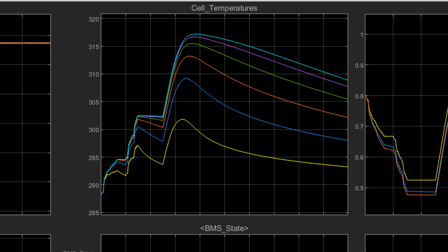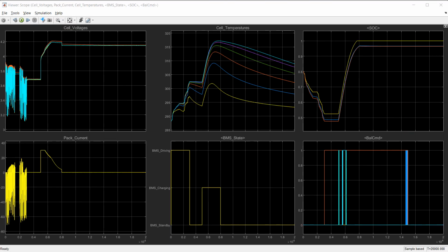Even when the maximum temperature reached during the simulation is not of immediate concern in terms of safety, the temperature difference exhibited here will eventually cause a much faster degradation of cell 6 compared to cell 1, leading to an undesirable unevenness in cell condition. Hence the need for active thermal management to keep thermal differences within a few degrees Celsius.